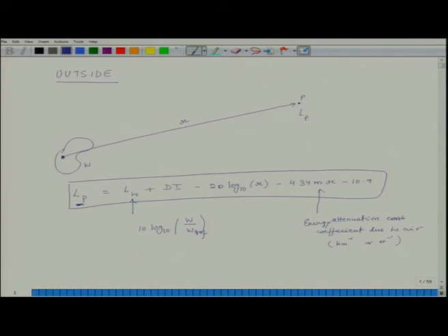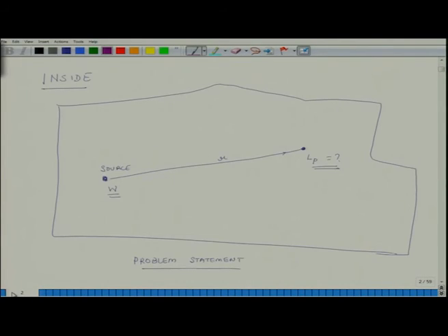In this formula there is the role for directivity index, because sound which is being emitted may be stronger in one direction compared to other directions, and if we are far away, then the sound pressure level will be less, and also you have the role of absorption of sound by air. Okay. So, in this case, what are different factors?